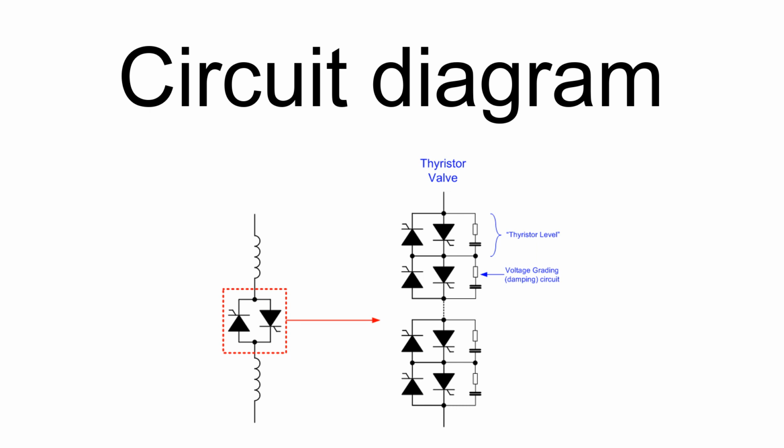A thyristor-controlled reactor is usually a three-phase assembly, normally connected in a delta arrangement to provide partial cancellation of harmonics. Often the main TCR reactor is split into two halves, with the thyristor valve connected between the two halves. This protects the vulnerable thyristor valve from damage due to flashovers, lightning strikes, etc.